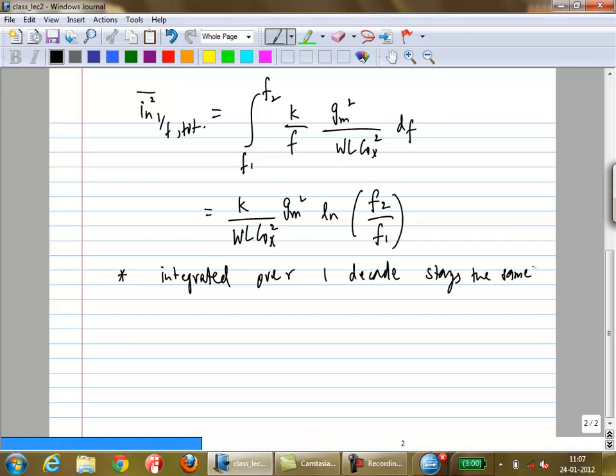Now a few days ago somebody had a question: what happens if you keep reducing the frequency, if you keep observing lower and lower frequencies? Obviously that means you'll need to increase your observation time. We looked at that. You can calculate what will happen if you assume a certain observation time and see how much extra flicker noise you add. Now that we know it depends on the decade, every decade you add extra noise, you can find out.